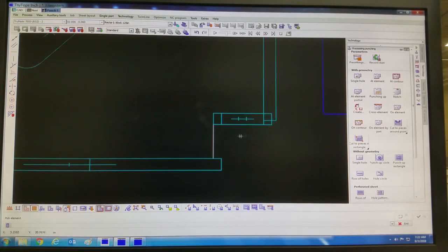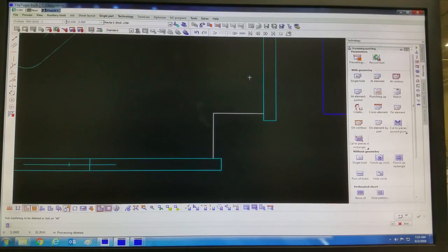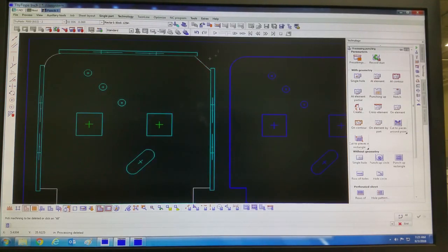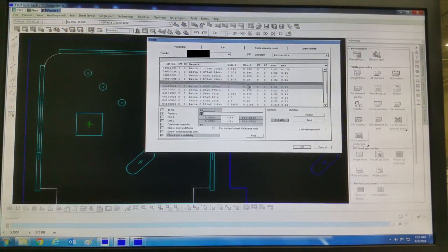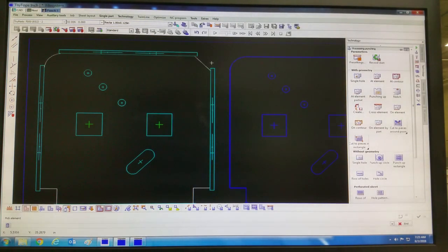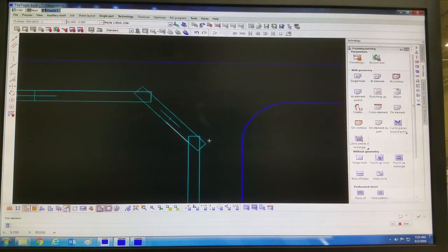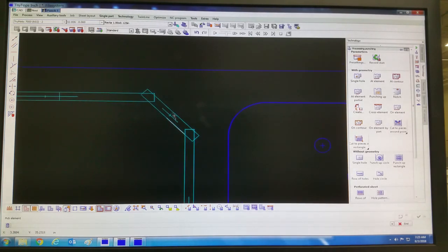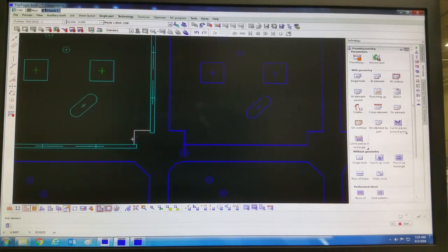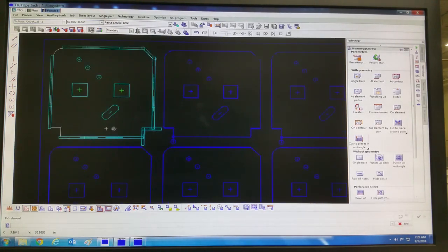Oh yeah, see, this tool is not good for this element. So I will delete it. I will choose a little bit bigger tool, 1 inch by 1/8. As you saw before, the 1/2 inch has to be used for 2 strokes. Now with the 1 inch, there is just 1 stroke. Do the same here, here.